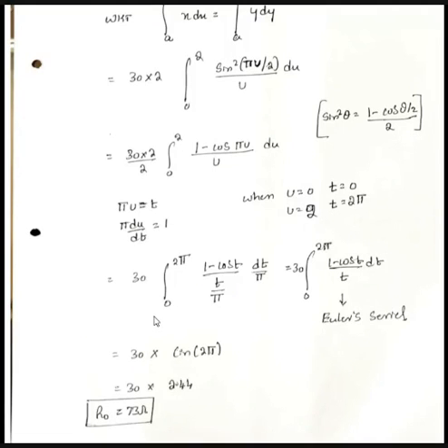Okay, so this is the end of these two topics which I wanted to discuss now. Radiation resistance of a short dipole, and radiation resistance of a short electric dipole whose length is lambda by 2. Remember, Rr is equal to 80 pi square L square divided by lambda square, and R naught is equal to 73 ohm, for the length L is equal to lambda by 2 here.